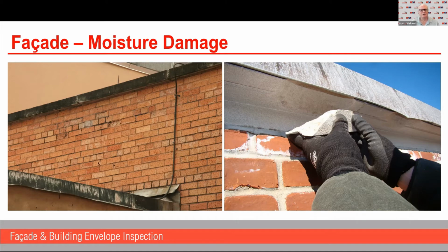The picture on the right is a capstone with some metal flashing on it, and somehow water is getting in there. It's either running through surface tension back underneath or getting in through the top, and that water, in this case, doesn't appear to be corroding the reinforcing, but it did manage to spall that concrete, possibly through freeze-thaw.